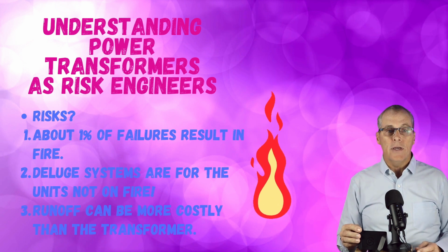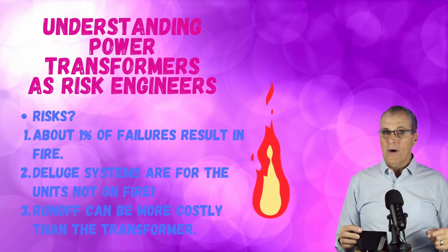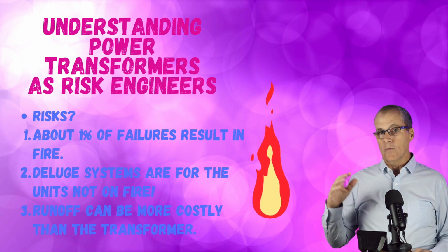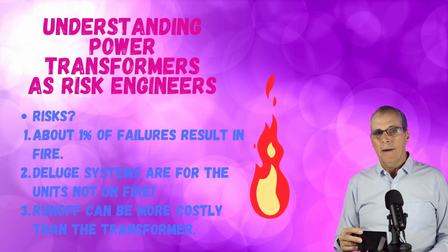We'll talk about that fire later. But the point is that the deluge systems are not there to put the fire out. They're there to protect the surrounding equipment. And sometimes, if you understand that, it helps with the design and what your intent is.